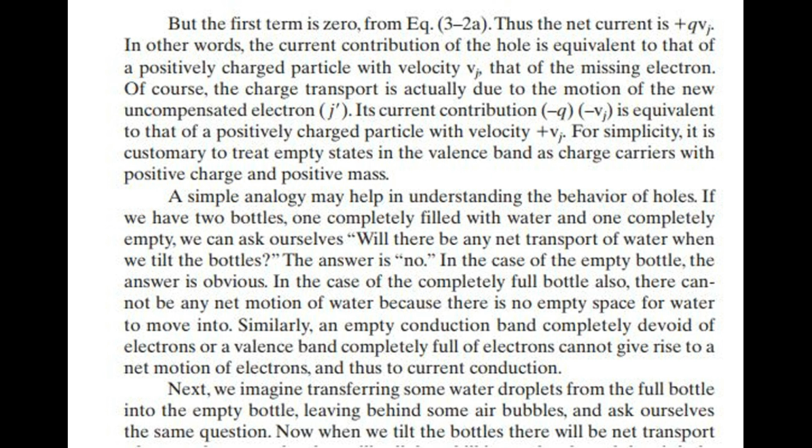The answer is no. In the case of the empty bottle, the answer is obvious. In the case of the completely full bottle also, there cannot be any net motion of water because there is no empty space for water to move into. Similarly, an empty conduction band completely devoid of electrons or a valence band completely full of electrons cannot give rise to a net motion of electrons, and thus to current conduction.